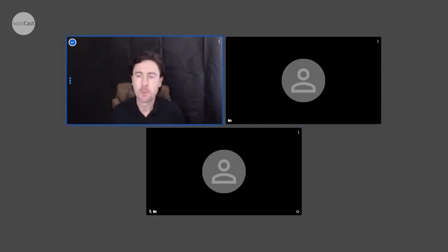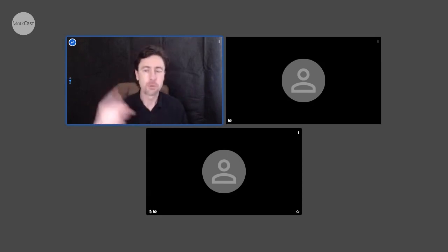Okay, so when we're doing RCM, we want to make sure that we only do RCM on the things that are really critical, because RCM takes a massive amount of time and money and effort. And if you all of a sudden go, here's our plant, let's make it awesome and do RCM, you'll never get to that end goal. So part of the RCM process helps us decide what's the consequence of that failure and how do we manage that consequence. So through that study, you need to iterate.